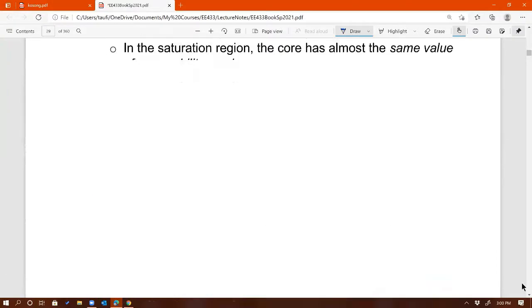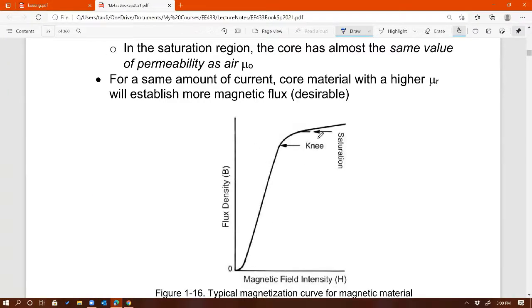But before I stop, if you look at the BH curve of a magnetic material, when it goes into saturation right there, guess what? The slope of this region where it saturates should be equal to the slope of what, based on what we learned? Free space, air. Exactly. That's why it's really flat. When you saturate, the slope is pretty much flat because that's 1/800,000, basically the slope of air or free space. Now your magnetic material becomes air. If you operate the core here, you're basically using an expensive magnetic material as air, or free space. So it's useless, and you're wasting money because of that. All right, enough.